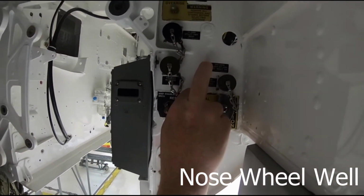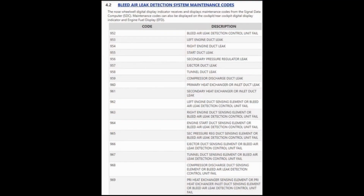Press switch and hold for 5 seconds. After performing your nose wheel well bleed air leak detection unit reset, perform your loop A or loop B test as applicable. To avoid unnecessary disassembly, before proceeding to MSP code debrief, common practice in the fleet is to slave in a known good element to test system circuitry and isolate failure to the wiring or element.